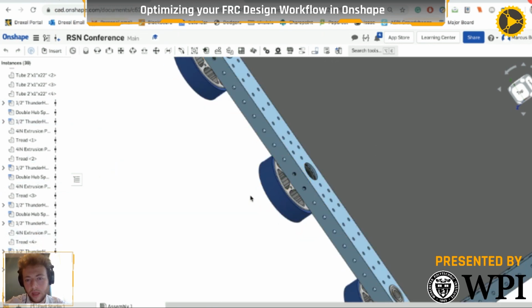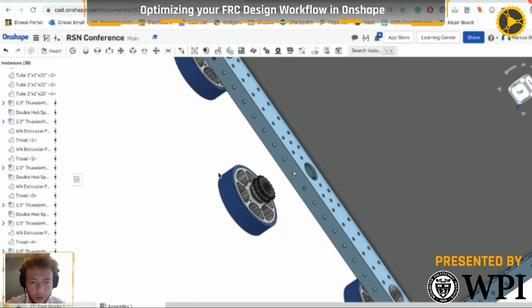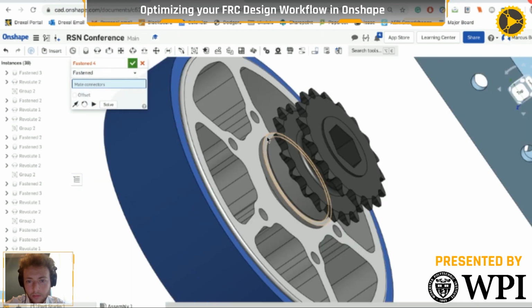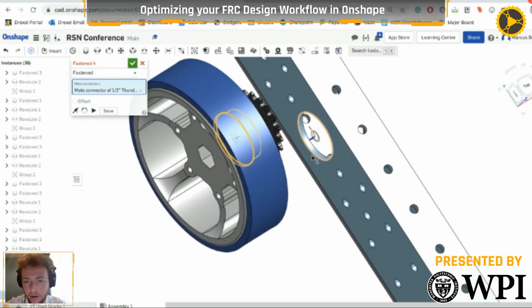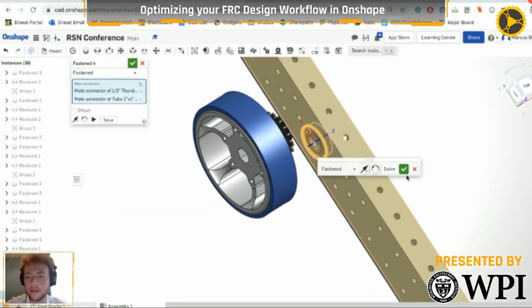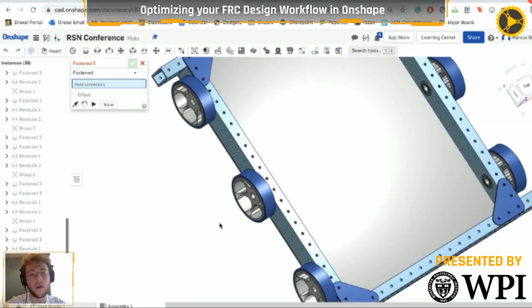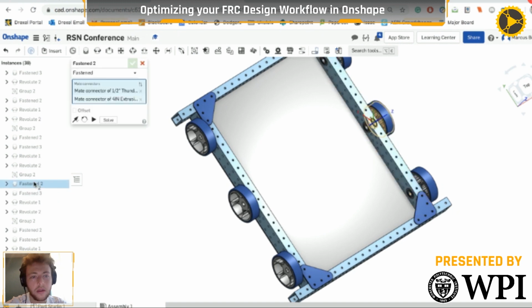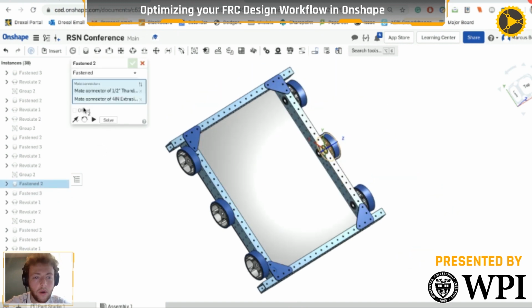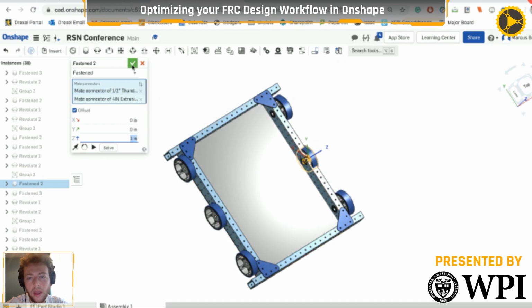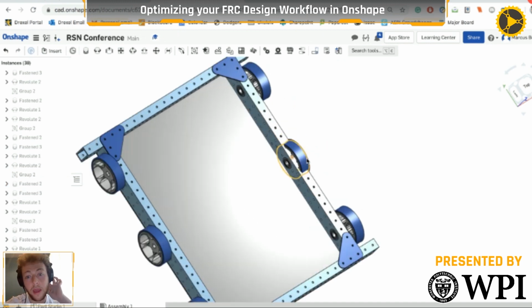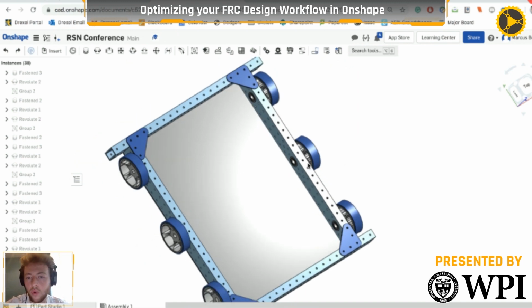Okay. I'm going to delete the rest of the mates. And obviously I could have set them up in a smarter way where it was based on this one, but whatever. I can now mate this, and obviously this is totally independent of the other. It's their own features, their own instances of the parts, their own mates. But I can also go into a mate that was created. I'll pick a random one, and I can set an offset of 1 inch. I can flip it. I can do whatever. And it's only going to make that change in that particular instance. So it's not creating things that are dependent on each other. And it's very robust if I want to make changes later on. That's what the tool is designed to do.